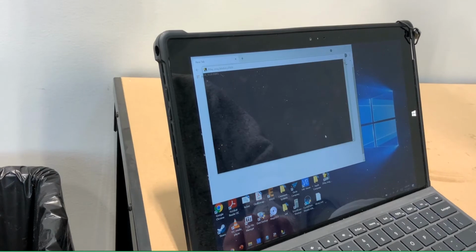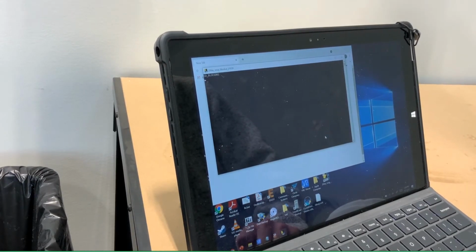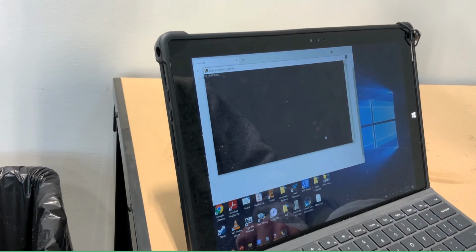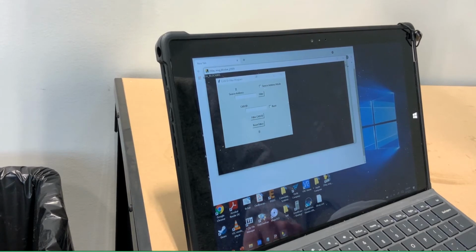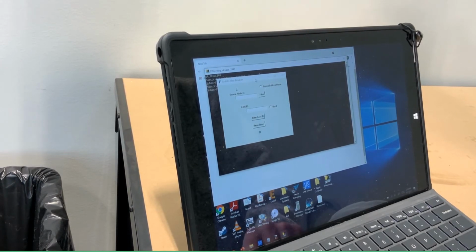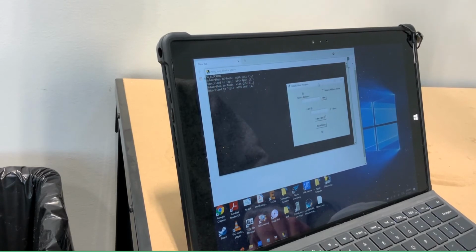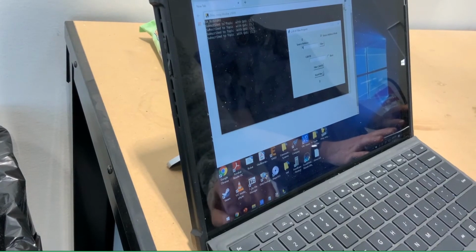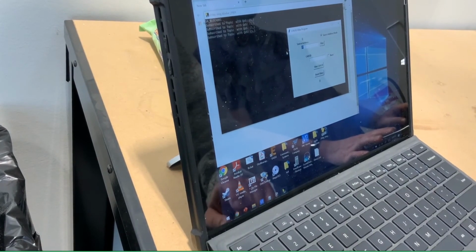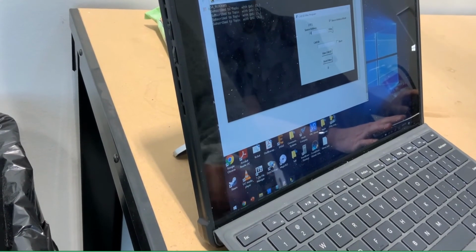Now it's connecting to that truck. Now entering the source address, which is the last two characters of the CAN ID, will allow two-way communication between the diagnostics end and the truck. Click filter.